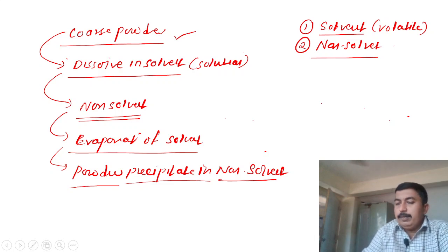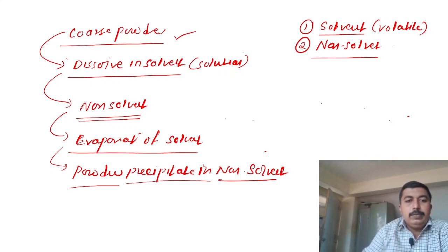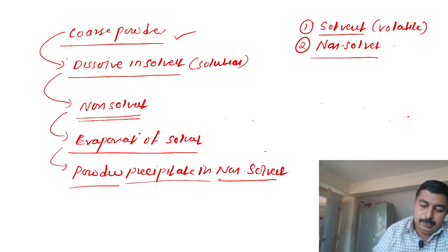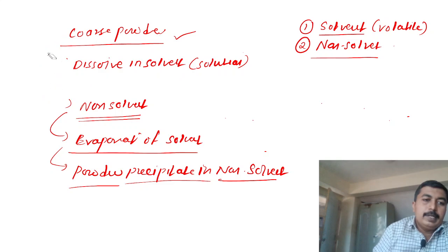In a simple way, you will get it. We just have to dissolve in a solvent. Later on, we have to add it to a non-solvent with continuous stirring. Evaporation of solvent takes place and the powder precipitates in the form of fine powder particles. This is simply a precipitation process of size reduction.